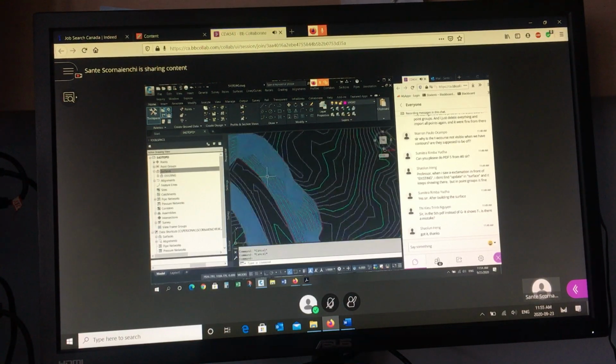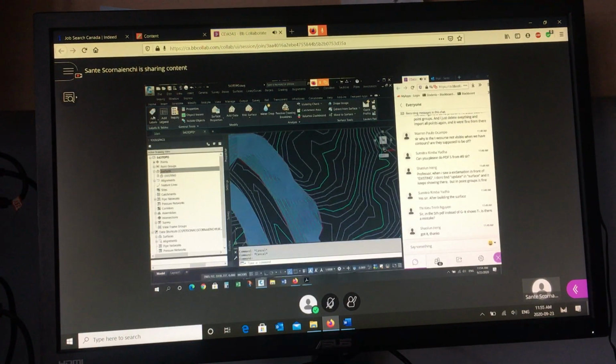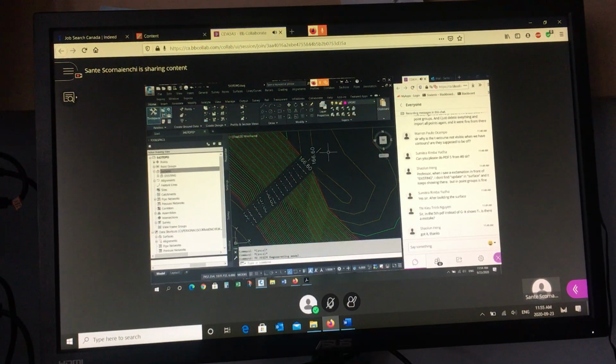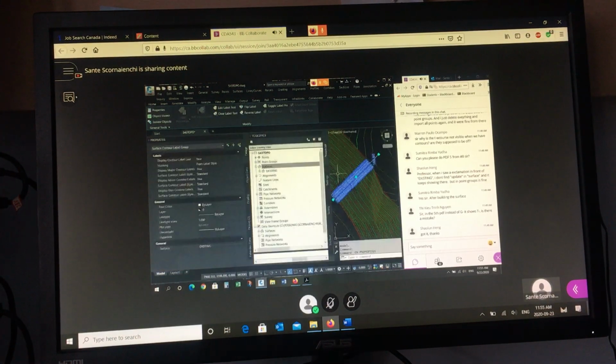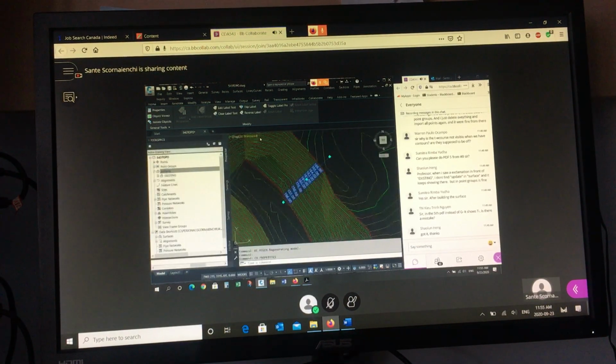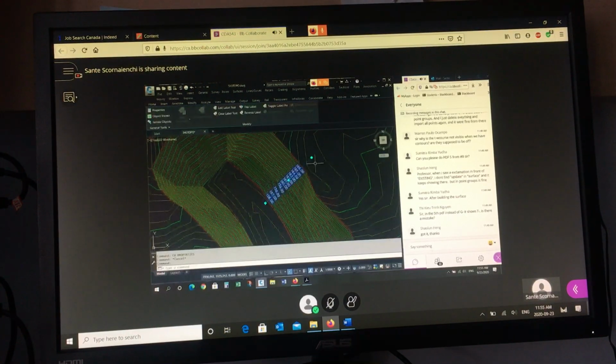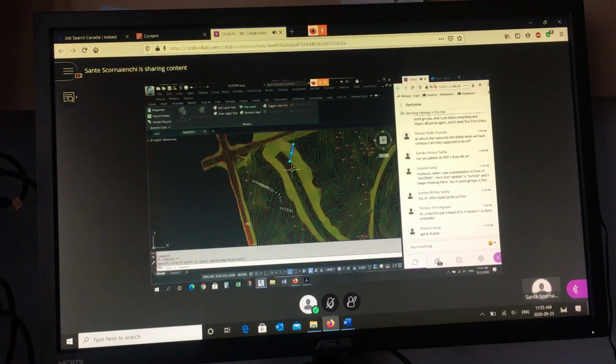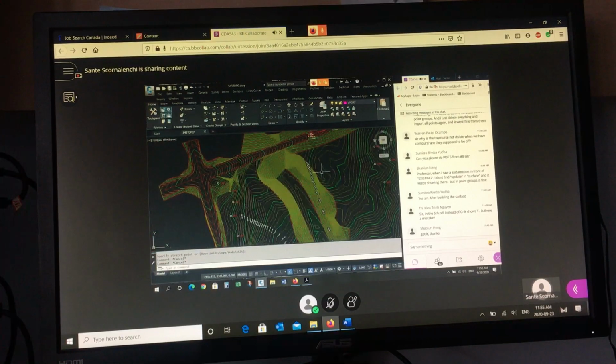And if you label a steep area, everything's going to be on top of each other. You can't read anything. In this particular case, if it's steep, it's tight density, turn off the line always, and then turn off the visibility of the minor contours. Only label the major contours. And that'll give you a little more space. And if they're still kind of crowded, in this case, I'll make an exception. Instead of going perpendicular, I'll go on a slight angle. That'll spread them out. It'll be a little easier to read. And these are just artistic presentation techniques that I'm giving you tips about.